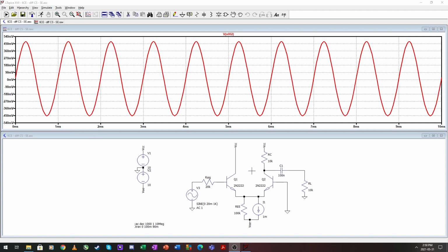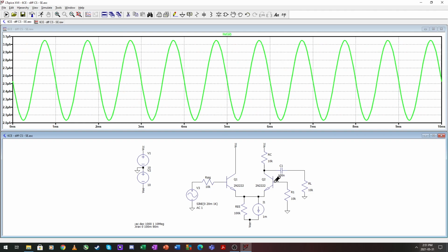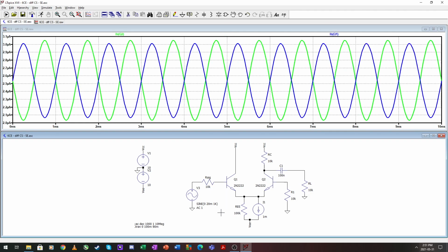So in the single-ended, we lose half our gain as well. If you want to improve this, again cater for the bias currents, and there we will have our full half a volt output from our 20 millivolts like that. So always cater for your offsets. These two will now be more or less on top of one another. Okay, so that is our single-ended conversion.